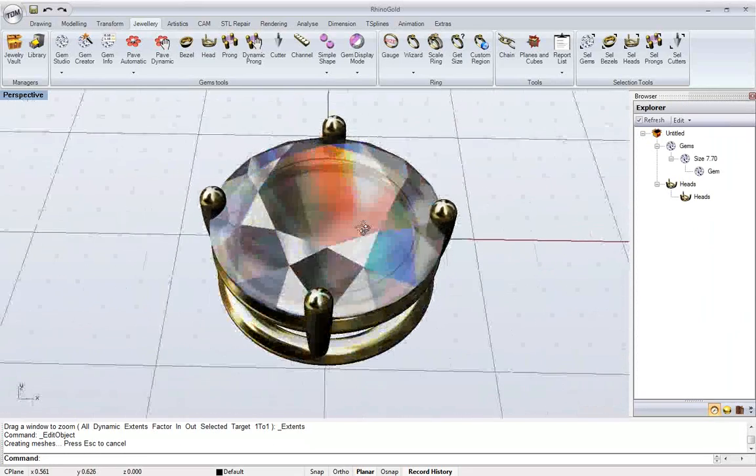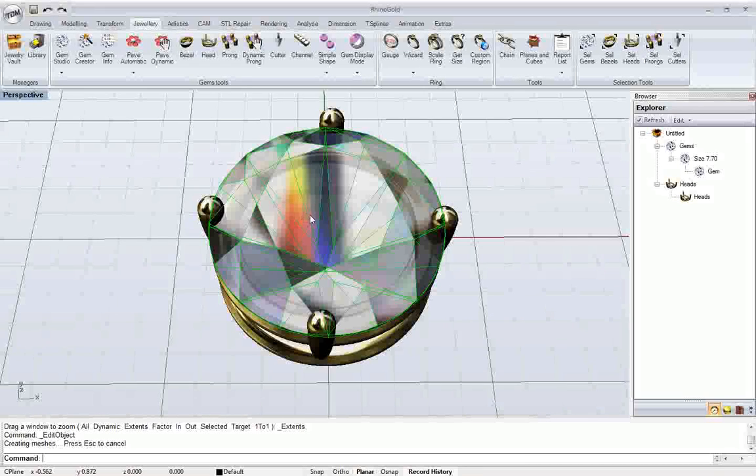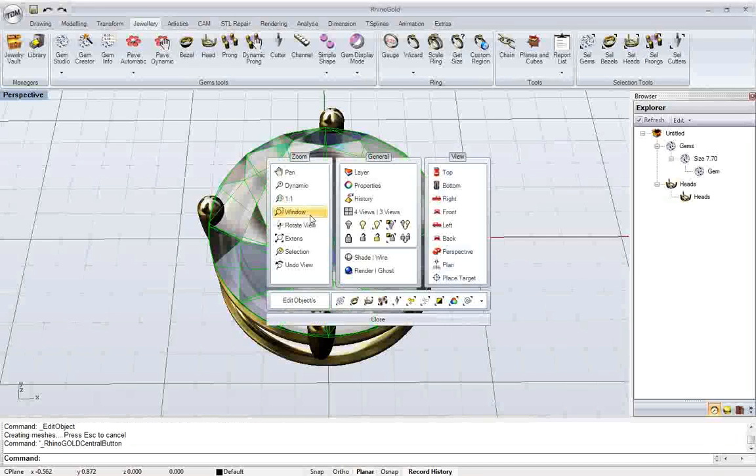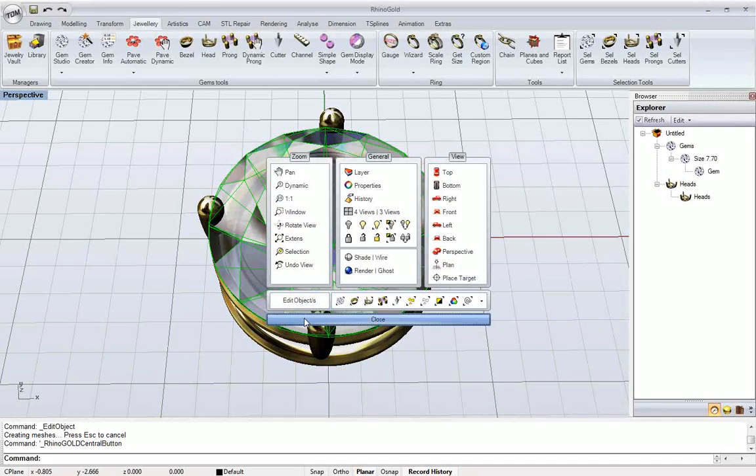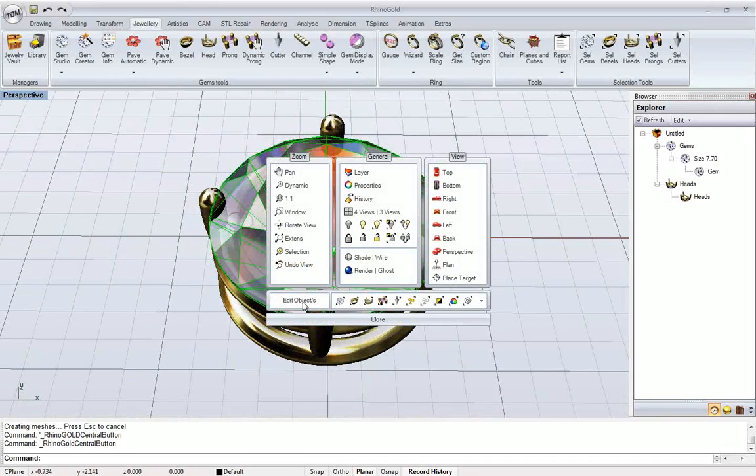Okay? Other way is directly select the object, press central button in the mouse, and edit object. Okay? If some users don't use mouse, use the trackpad, they can press F4. Okay? The key F4 is exactly the same. Okay? And then edit.